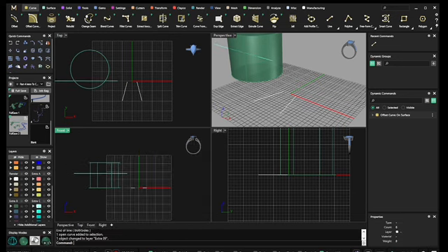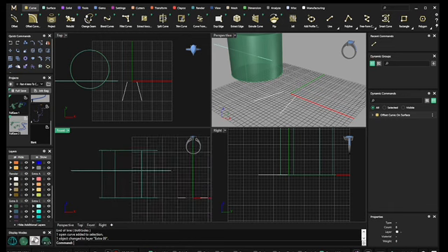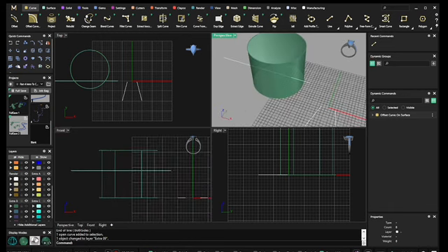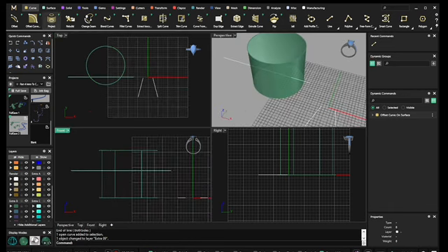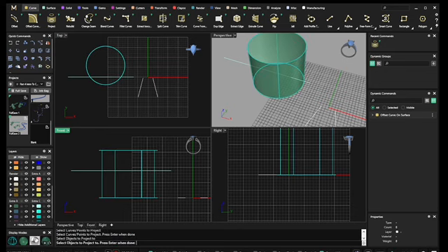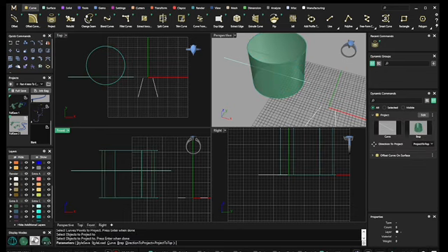I changed the color to a very light turquoise so you can see it. And let's click on that again. Project. Select curves. Press enter when done. Select object to project to. Now, where you're at and what viewport you're in makes a difference. At least it does in the non-dynamic project command. So let's see what happens here. I'm going to select the object, press enter.